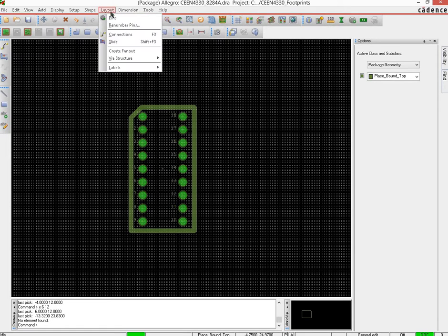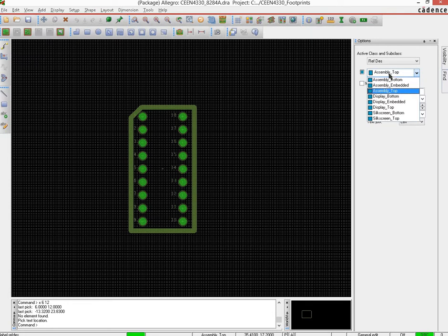And then we have to put reference designators at minimum. Those would be under layout, labels, reference designator. The first thing that you would designate is silkscreen top. Do confirm that your marker size is something which is non-zero, and then come close to where pin 1 is and click there. You would see a cursor. Then just type out, since this is an IC, a U question mark. Now whatever name you give, remember to put a question mark at the end.